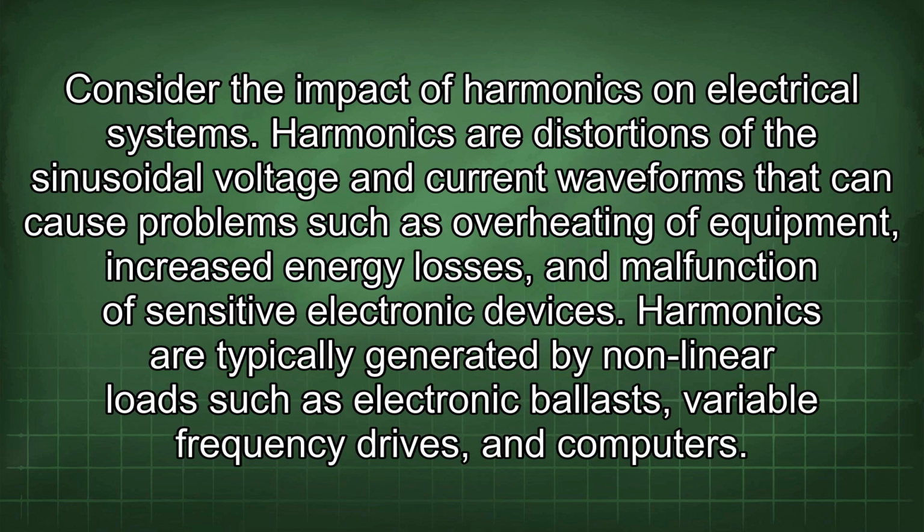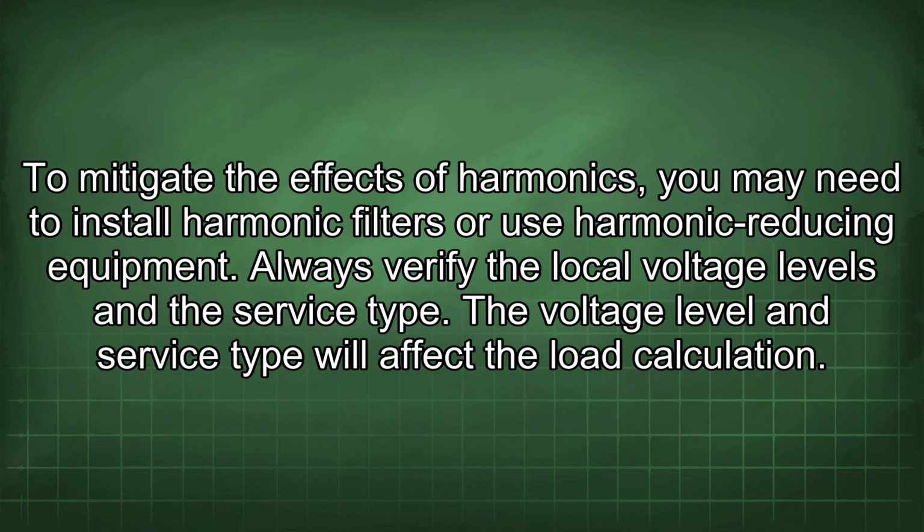Consider the impact of harmonics on electrical systems. Harmonics are distortions of the sinusoidal voltage and current waveforms that can cause problems such as overheating of equipment, increased energy losses, and malfunction of sensitive electronic devices. Harmonics are typically generated by nonlinear loads such as electronic ballasts, variable frequency drives, and computers. To mitigate the effects of harmonics, you may need to install harmonic filters or use harmonic reducing equipment.